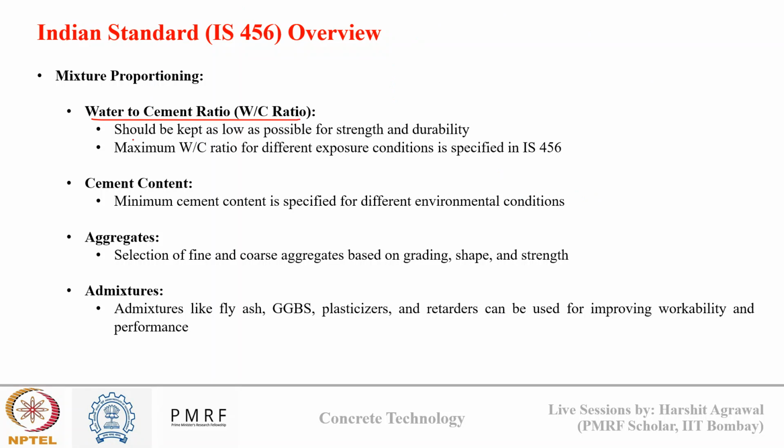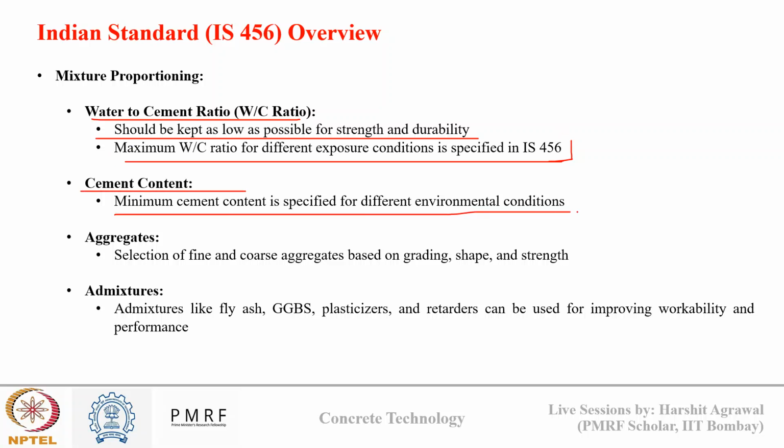So it should be capped as low as possible for strength and durability. And maximum W by C ratio for different exposure conditions is specified in IS 456. So this we will see after a few slides. Then cement content, again, minimum cement content is specified for different environmental conditions. Again, this point we'll see later on.